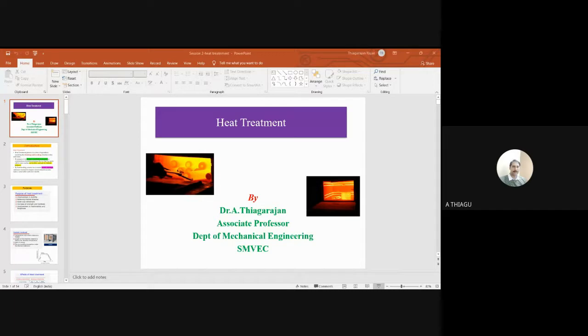After completing the heat treatment process, you can look at the microstructure and find some spherical shapes of carbon. If you perform this kind of application, ultimately the mechanical properties of softness and ductility will be improved or increased. Shafts and gears are essential applications. Toughness and ductility will be improved, along with machinability and formability, which is very important.